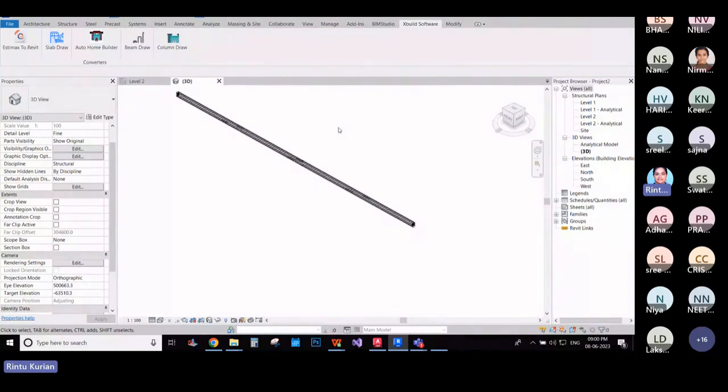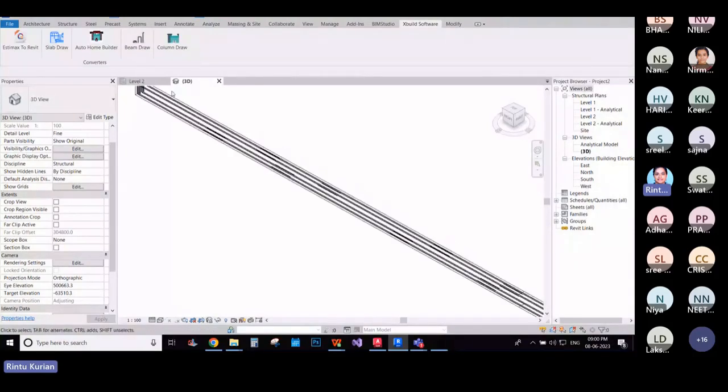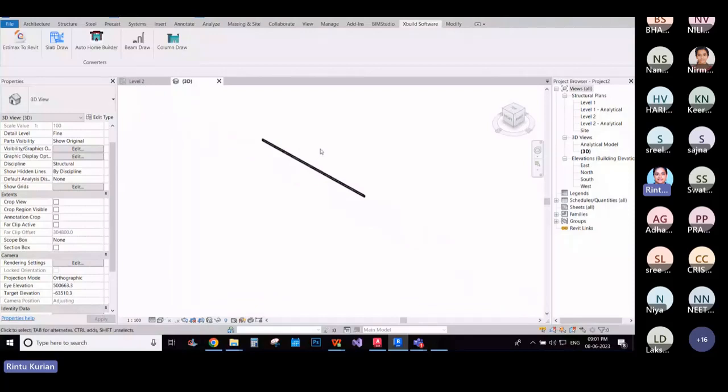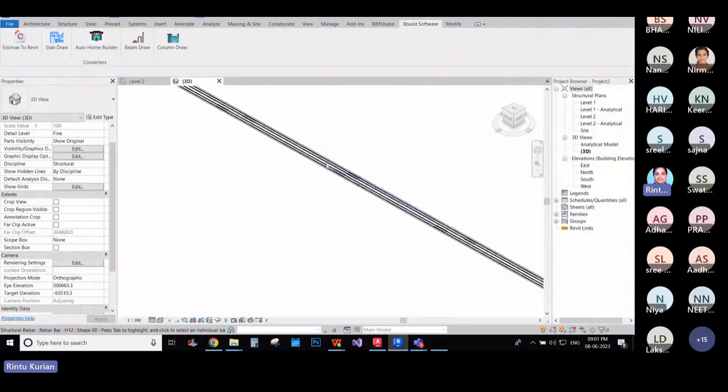To begin with, it will be better if you learn to draft or model the bar on your own, so that you will be familiar with how to handle situations for different structures like a footing, a pile cap, a pile, a circular column. These are not the typical ones. These are different structures that can challenge you with different rebar modeling. All these can only be done manually.